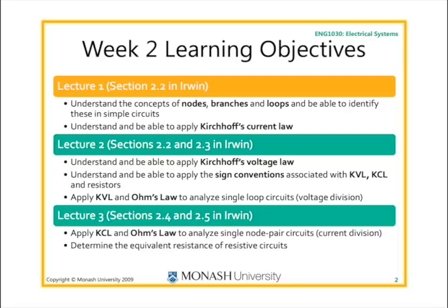You just have to do one Kirchhoff's current law at the top or bottom node here. There are only 2 nodes again. Just have to apply Kirchhoff's current law. The only slight complication, not really one, there is a dependent current source over here, but that's okay. Just write down the sum of the currents entering the top node is 0, and you'll get an equation, and you can solve for IX, the mystery current. So see how you go. You can have a chat, take 30 seconds, 40 seconds, even a minute.